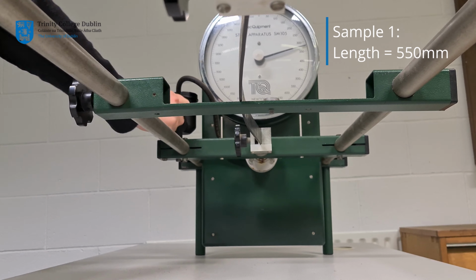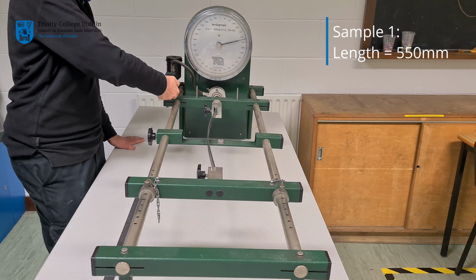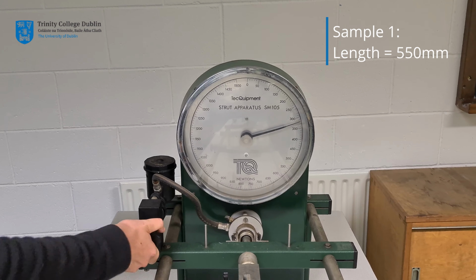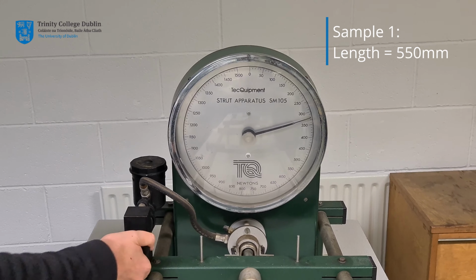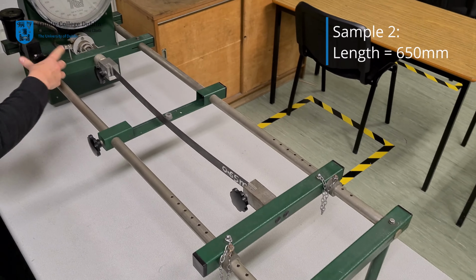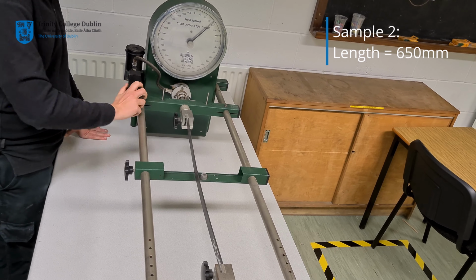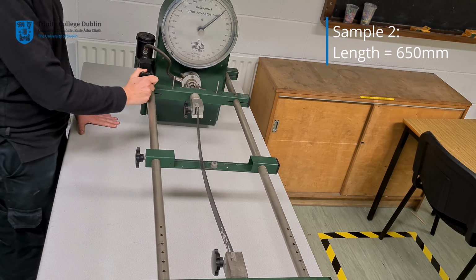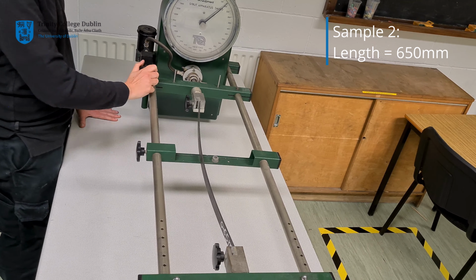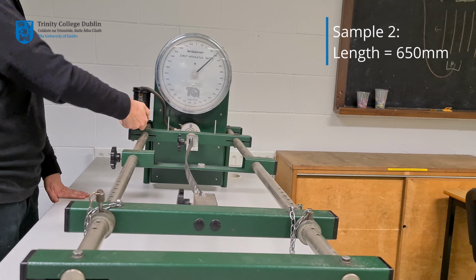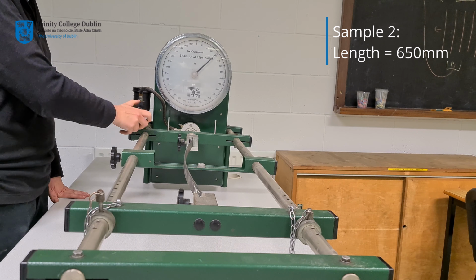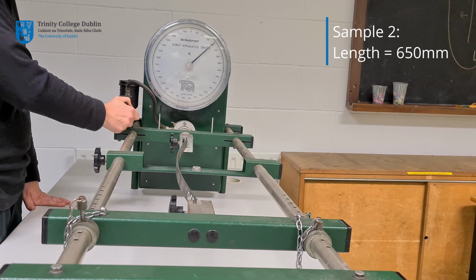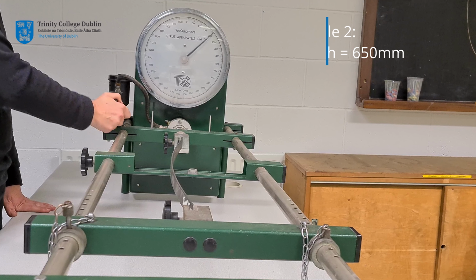Upon reaching the critical buckling load, the steel members are observed to buckle or deflect from the centre line. Please note the value observed for both specimens. You will need these force values for your calculations. Please also calculate the slenderness ratio and the radius of gyration from the given dimensions.